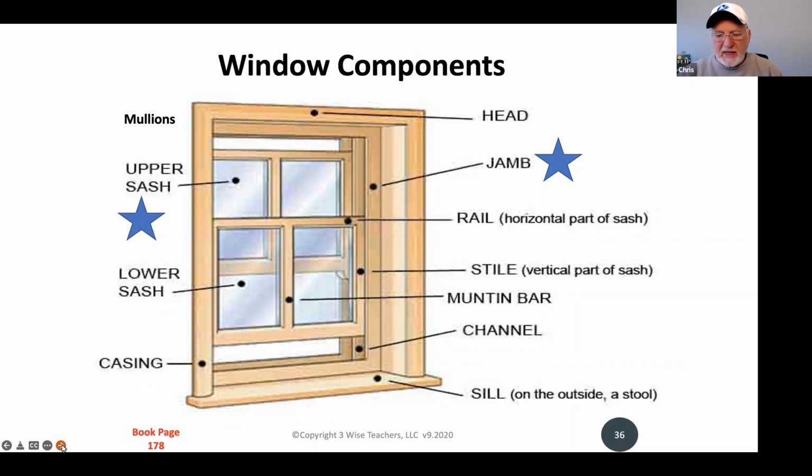Kind of rare that the words mullions and muntins would pop up. But if you ever see the word mullions and muntins, there's a good picture here of a muntin, but not of a mullion. You see it pointing to that. If you ever see a question about a muntin, it actually separates the window panes. Mullions, you often see if there are multiple windows side by side, it's the bar that separates actual windows, but the muntin separates the window panes.